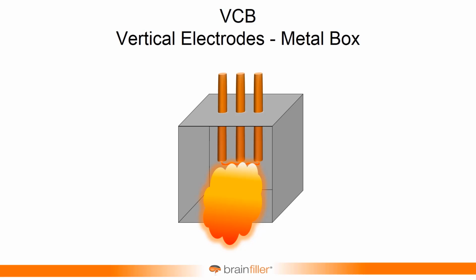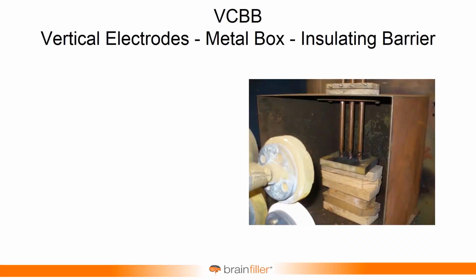So we still have that configuration for the next edition. And then we have a configuration for the insulating barrier. Now this was a test setup from several years ago. Again, this isn't the exact setup from the new standard. There are pictures for those test setups that you'll be able to see with the new standard. But it's pretty much the same kind of idea. And so what happened is there was this thought about what if the conductors terminated into an insulating barrier. And this is representative of certain conditions in some types of equipment. And the thought was the arc energy would be running down the bus, and it would hit that barrier, and it would balloon out and basically come out a little more aggressively.